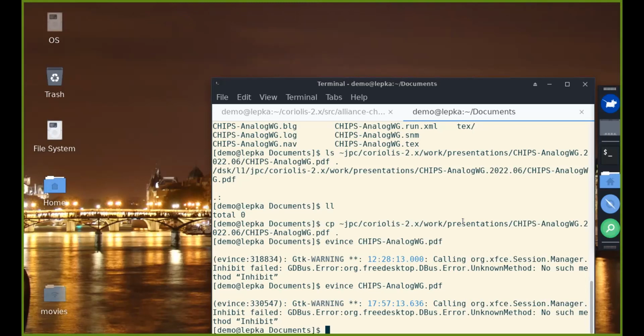Yeah, hi, this is Boris Merman. One quick question. The layout you showed, it looks like it's all minimal routes, minimum width wires with one contact. How do you deal with higher current densities and IR drops and things like that? Or wider traces, right, if the designer needs them? We can handle non-default width wires.